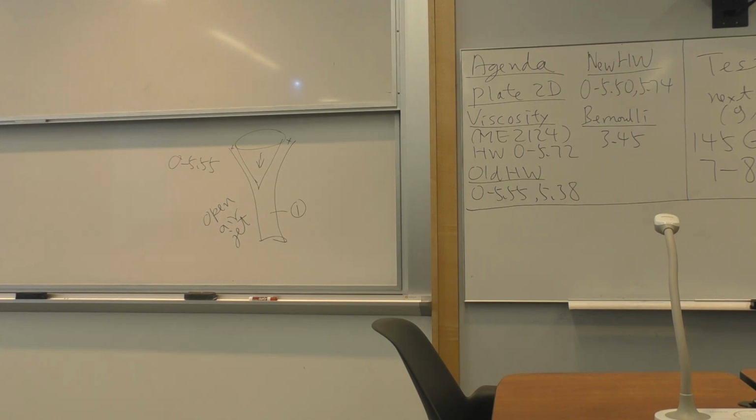And you're told in the problem statement it is 40 kilopascal. And that is the pressure needed to push the flow to come out from that nozzle. So an open jet versus a contained plumbing is totally different. The pressure inside this plumbing is anything but atmospheric. And you either have to calculate that, maybe use Bernoulli, or it has to be told. All right, so make sure you understand all those details.